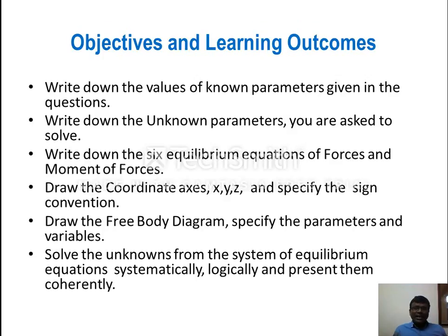Once you understand that, write down the unknown parameters you are asked to solve. There are known parameters, and there are unknown parameters which you are supposed to solve. Write down the 6 equilibrium equations of forces and moments of forces. That's a task. You have to write whether it is a static equilibrium or dynamic equilibrium. There are equilibrium equations available, so you have to write down all the equations carefully.